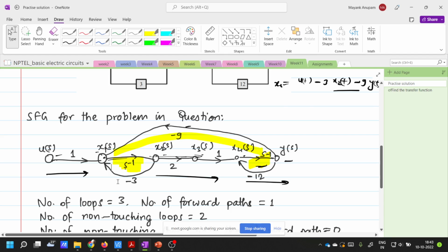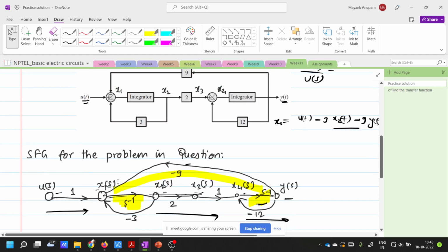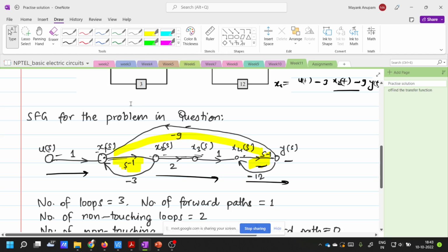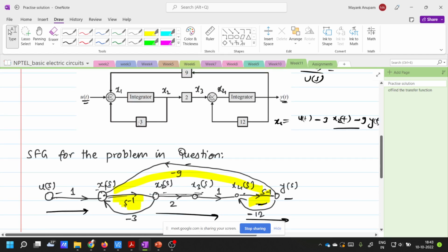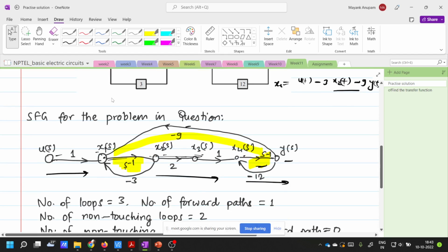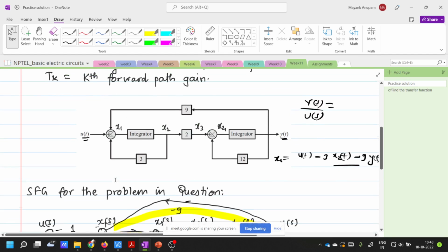So if you want to subtract something, you have to include that -1 sign in the system gain itself. X2 is multiplied by 3 and then subtracted at this node to result in x1. So what we have done here is multiply x2 by -3 and then simply add it to this node. They basically mean the same thing.